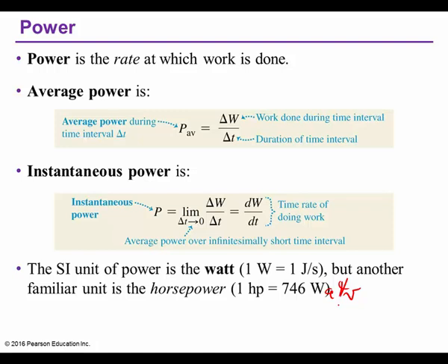Walk-in cooler, low voltage? Yeah. And it's going to burn the compressor out because the compressor is built to operate at 220. And sure enough, it was 190. Dad checked it again, 190, and another time maybe 195, and another time 190. And he called the power company. He said, look, y'all have got to get over here and replace this transformer. Because if you look right behind the cafeteria, there's a bank of transformers, 3 on a pole. He said, we've got a bad transformer. We're burning out compressors. Come over here and check the voltage. And sure enough, they said, well, Melvin, you're right. And so they replaced the transformer and fixed the problem.